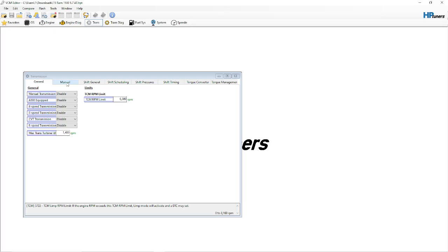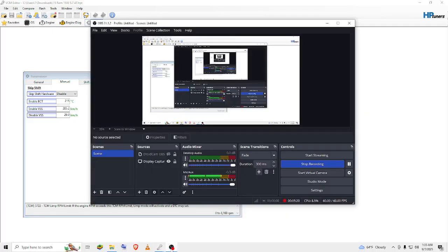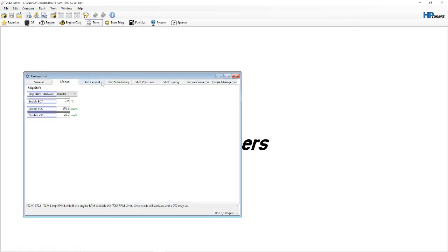Perfect example, BMWs, GMs, Alfas. Pretty much everything's controlled off a module rather than a relay and a fuse. They go bad, but typically it's a software glitch. A lot of the transmission issues, like on the Dodge Sprinter vans, can typically be solved and protected by an electronic update through the TCM or PCM, the powertrain control module and transmission control module.